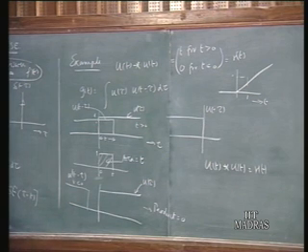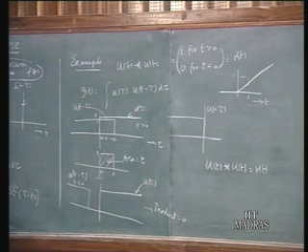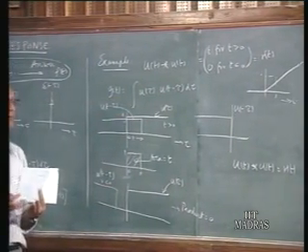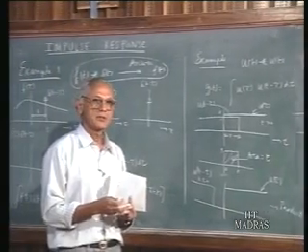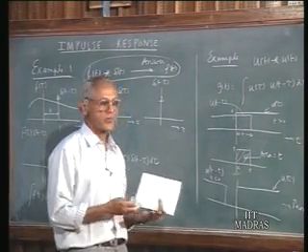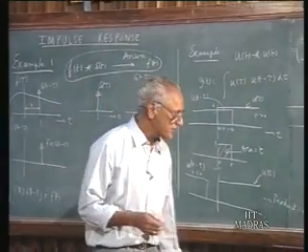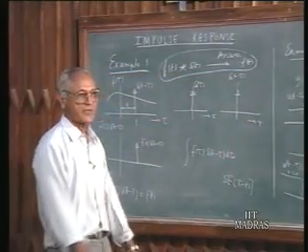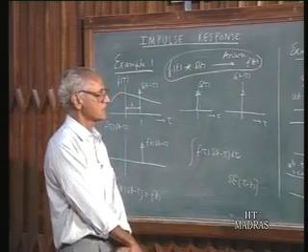So the idea of convolution is relatively easily seen in simple cases by plotting these graphs in this manner. Again the key words are fold, shift, multiply and integrate. Integrate means finding out the area under the curve. For simple geometries the area under the curve can be easily found out without doing integration, and you can picture what the final result is going to be using these concepts.